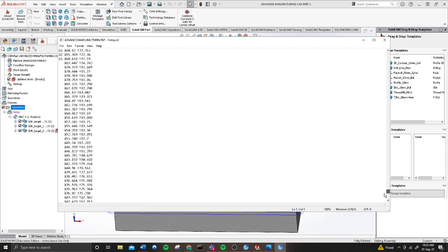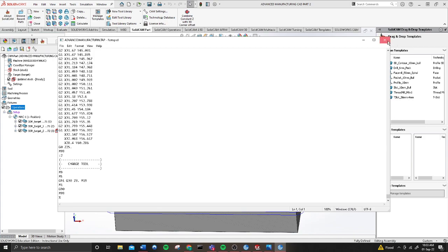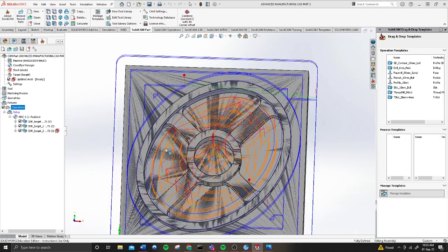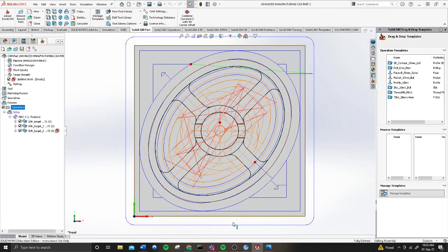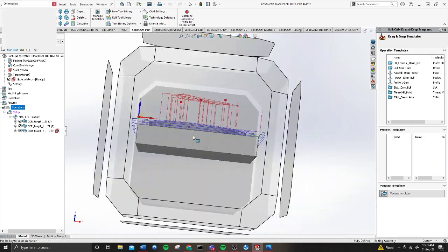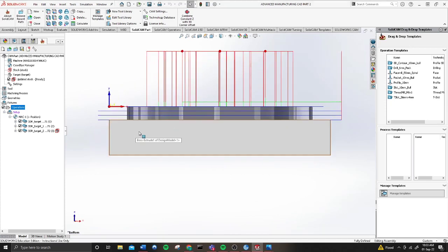So for this component here, the clamping positions are going to be at the bottom and at the top, and that's going to be sort of reflected in the report. In terms of how high up the part they're going to be going, they'll be sort of 3/4 or 2/3 of the way up the part, just so they're not interfering with these tool paths here, and that the clamp's not getting affected by that.